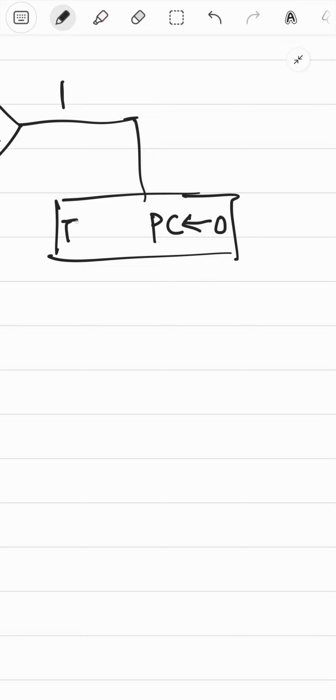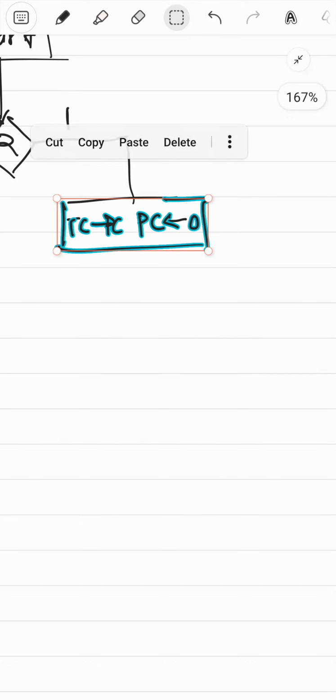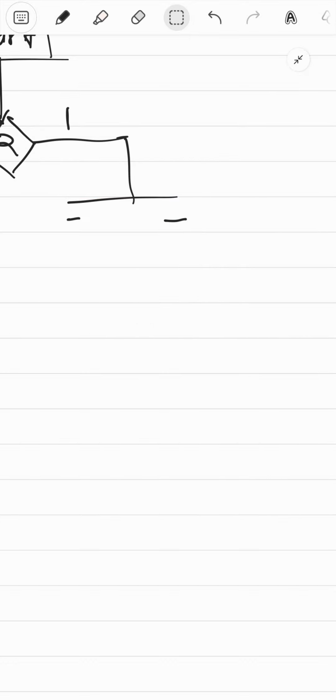But we also set this thing. Or okay, let's not set it to be 0 exactly. Well, never mind. I don't know if this is correct. Yeah, I don't think this is correct. So you can't clear the program counter at the same time as sending its value to something else. So instead, you take the temporary register and then you give it the program counter's value. All right.